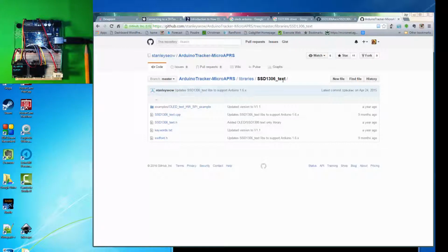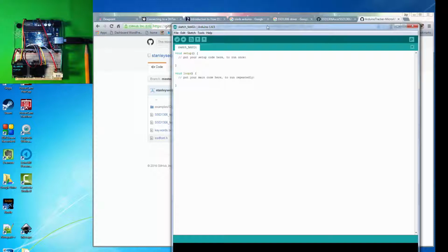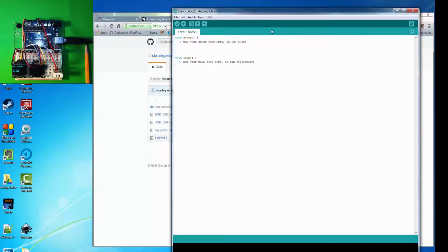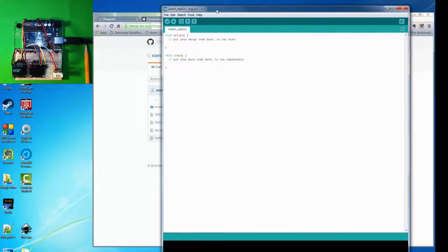A lot of people are wanting to put graphics and fancy stuff on their LEDs. For most data acquisition, we just want to put text, that is letters and numbers. And so we can use much smaller libraries and avoid taking up a lot of memory in our Arduino. So that's why I picked these two and wanted to show you how to use them. So you need to download those files and import them into your libraries.